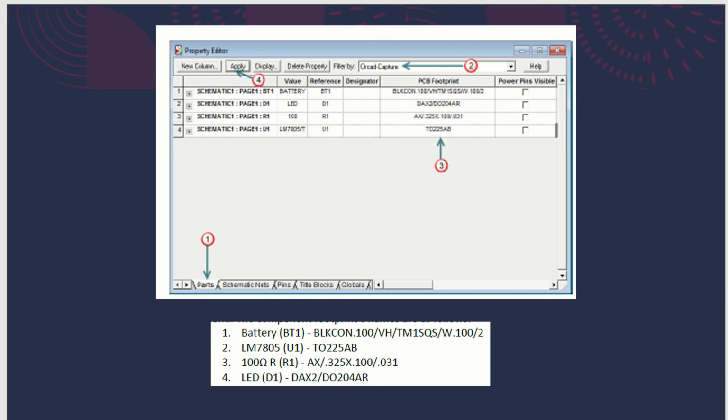First thing that you need to do is input the components' footprints. One of the important pieces of information contained in the layout netlist file is the actual physical dimension and specification of a component. This physical information is called a footprint. A footprint is the physical description of a component and it consists of three elements, which are pad stacks, obstacles, and tags.